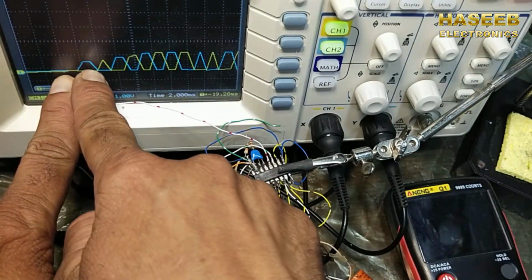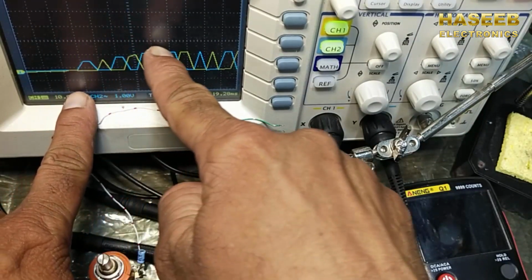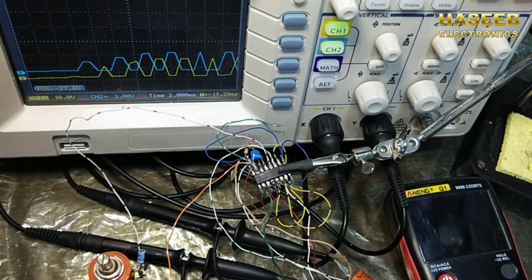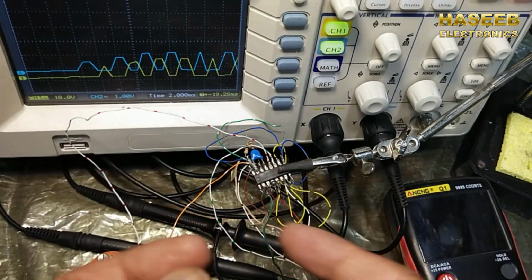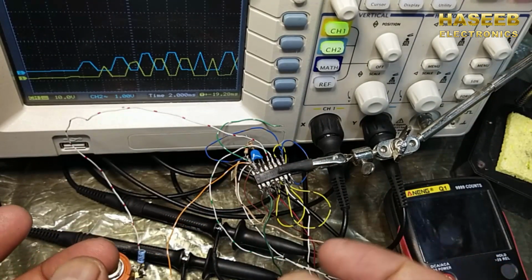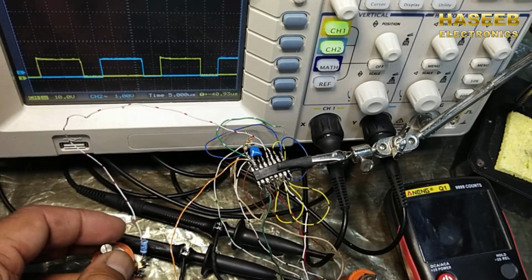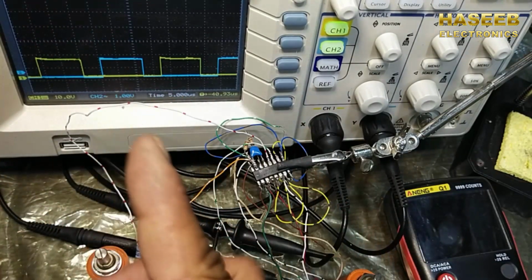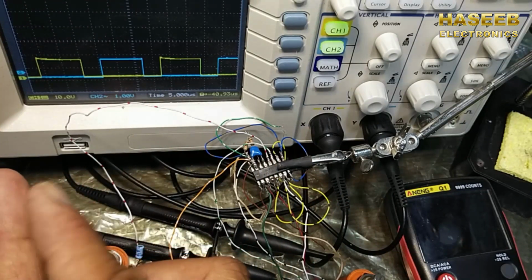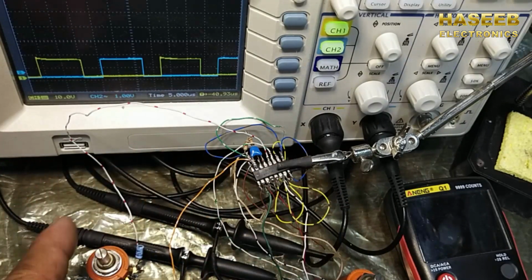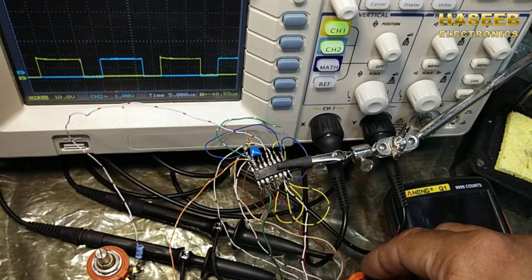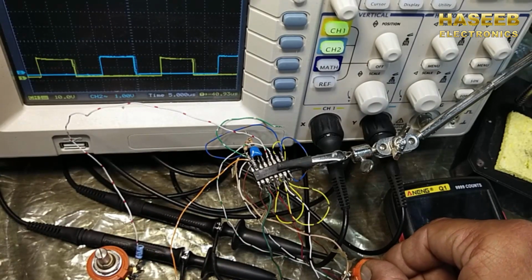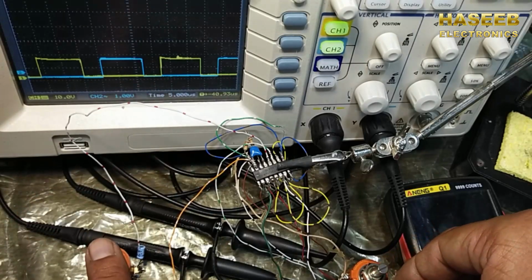In the next startup, it works the same. So that is the function of the soft start. In this video we discussed soft start and dead time control. Here we can adjust the dead time. Dead time will limit the duty cycle within 0% to a specific level which we adjust from here. But this feedback control will adjust the duty cycle up to the limit which we have set from here.